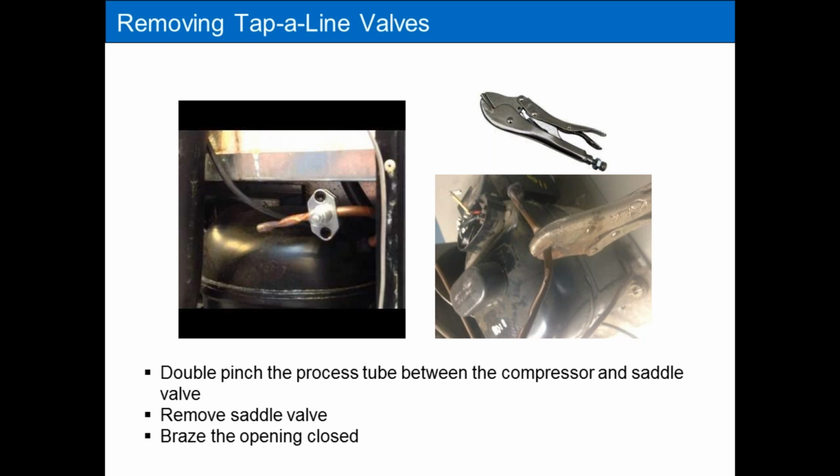So it is possible to take off your saddle valves using a pinch-off tool on an operating system. It's extra work, but it's good practice because those saddle valves are not really designed for long-term use. They will leak over time. Maybe a year, 2, 3 years down the road, they will probably leak. So if you can take them off, you're doing your customer a great service. Do you have to take them off? That's your call. Would I recommend it? If you have the time and you can, absolutely take off the saddle valves.